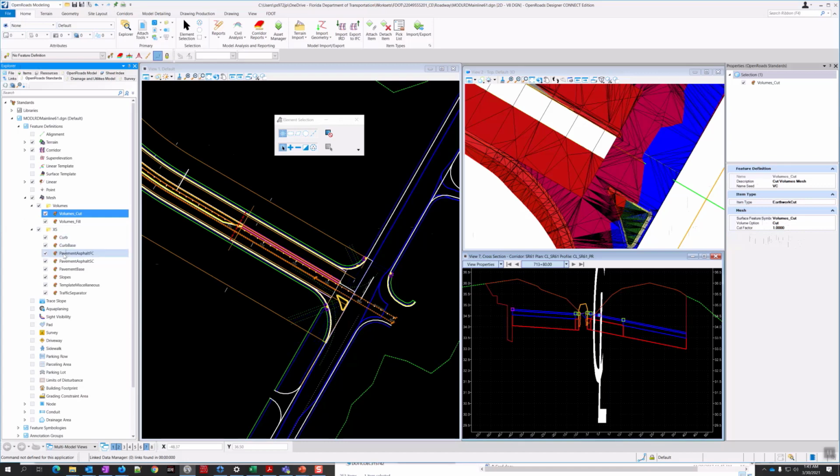But the other thing I want to point out on these other meshes, if you say, let's pick payment for example, there's a volume option right here under the mesh. This is what's used to determine, is it existing, is it design, is it subgrade, is it unsuitable material. So you can change the classification. This was called classification if you did the earthwork calculations in SS10. That's what it would have been referred to as. So it is important for your existing features to be in here as well.